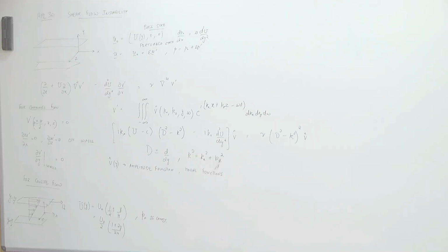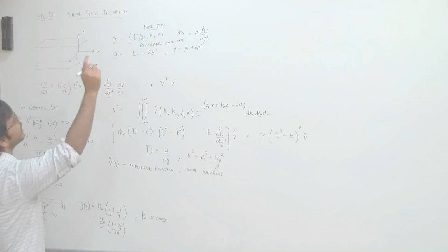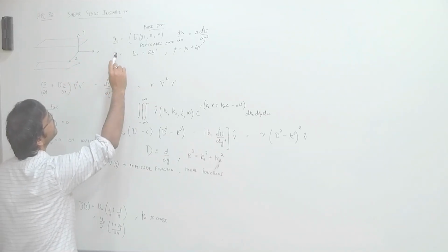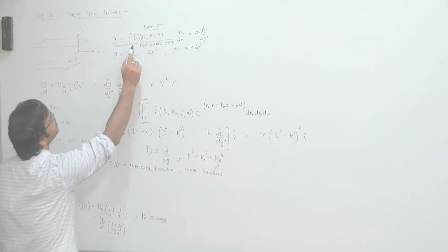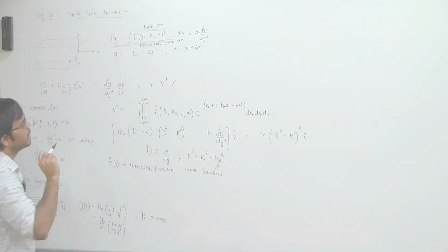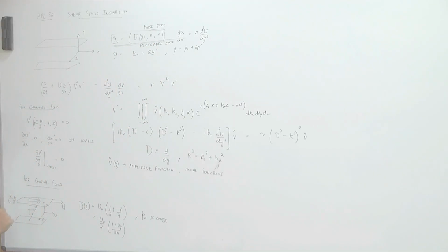Okay, so stability corresponds to analysis which is on top of whatever we have done so far, that is finding steady laminar solutions. We are trying to derive stability of those. So similarly for boundary layers also you could understand stability, and if you look at our boundary layer equations, you will see that you can study stability by making this assumption particularly. We will discuss that after we discuss Couette flow.